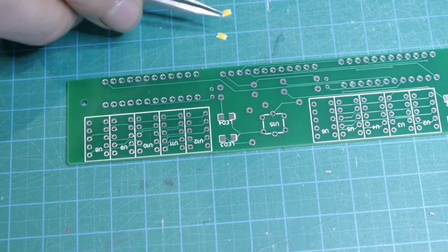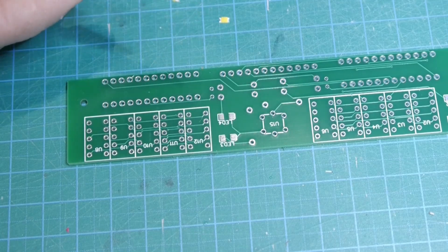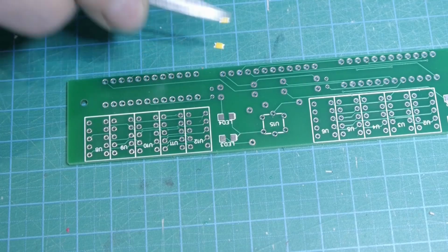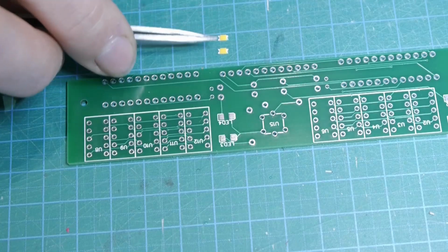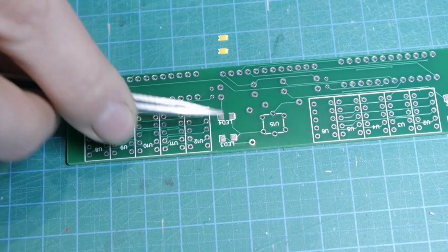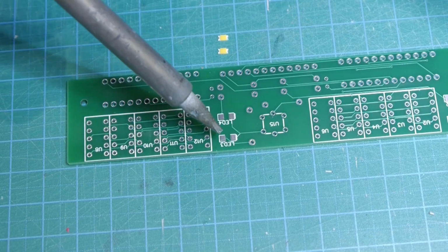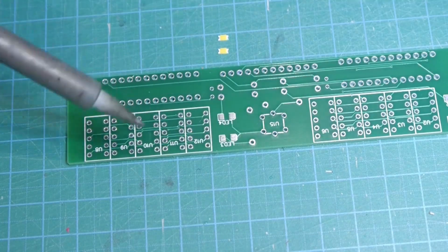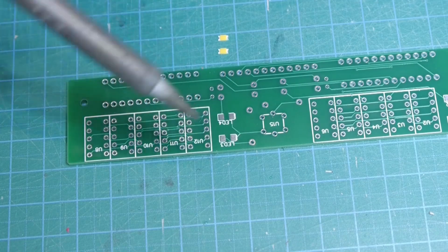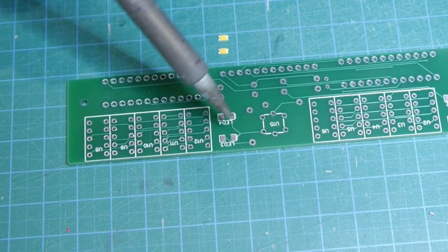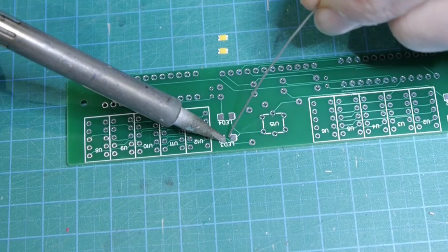There they are. There is a little green dot on one side here, which will show me that this will be the ground pin here. So this will be the orientation in which I will mount the LEDs later here. And now I will apply solder on one pad here first. The reason why I'm mounting the LEDs first is that now I'm able to reach here without any interfering objects. So now applying a little bit of solder